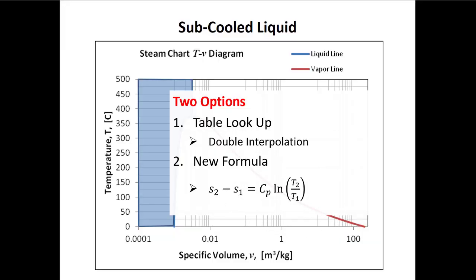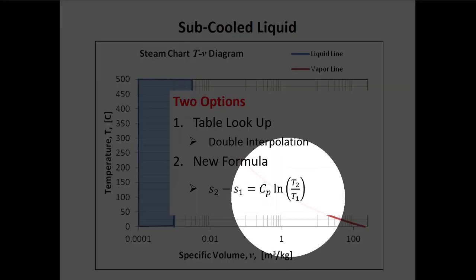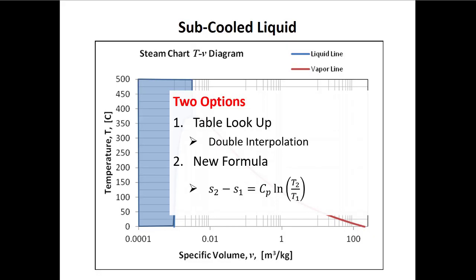This looks a little bit like delta H is Cp times delta T, except instead of delta T, we have this natural log of the ratio of the temperatures. Again, your spidey sense should be tingling here because neither of these two temperatures is a delta T, so that means we need to use absolute temperatures when we're finding the ratio.